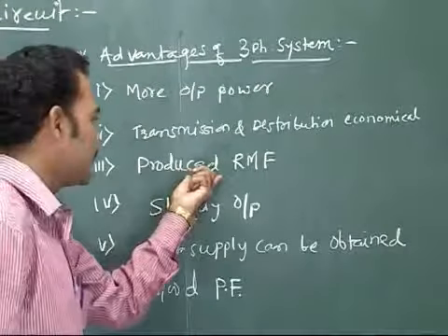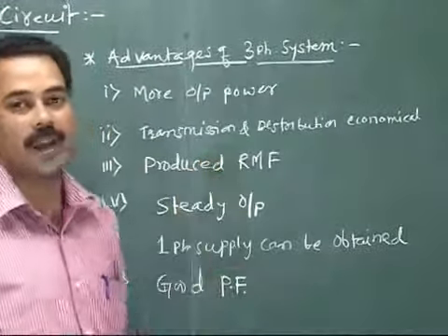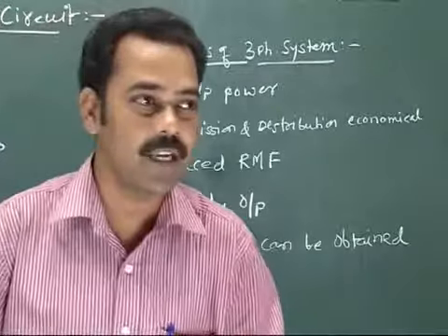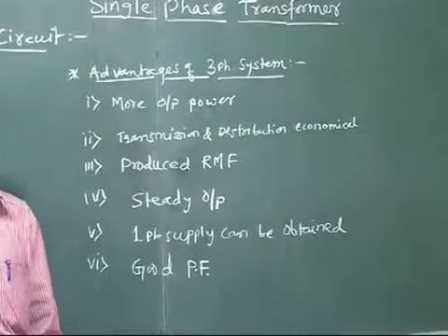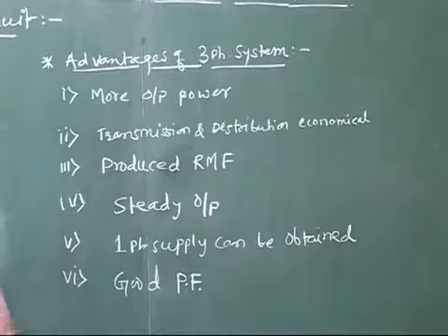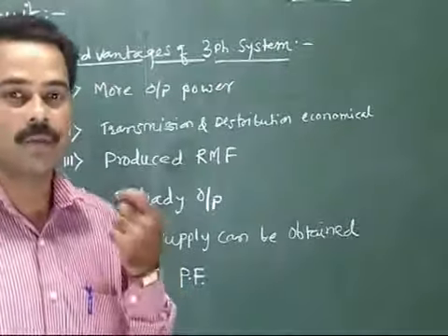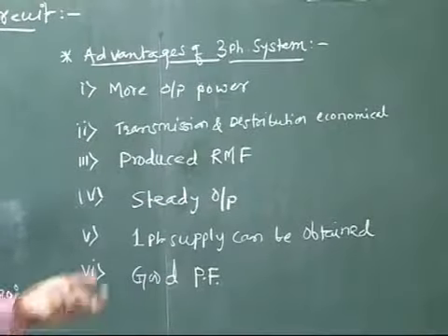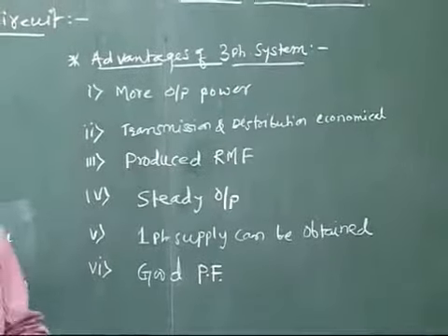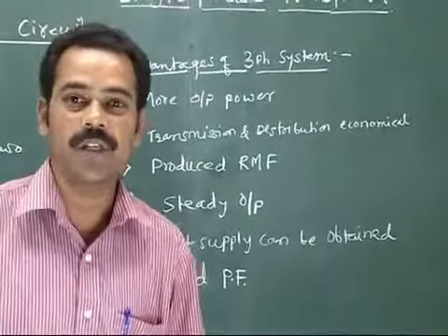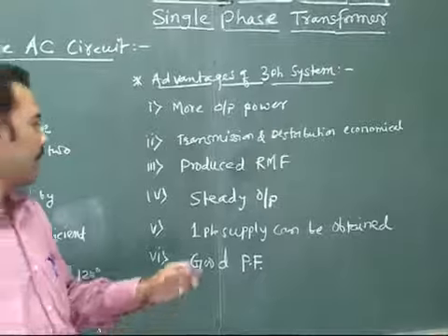Third advantage we can see is the rotating magnetic field produced, which does not happen in the single phase system. In a single phase system, a rotating magnetic field is not produced, whereas a three phase system produces a rotating magnetic field, which is very important for induction motors, because an induction motor is self-starting due to this rotating magnetic field.